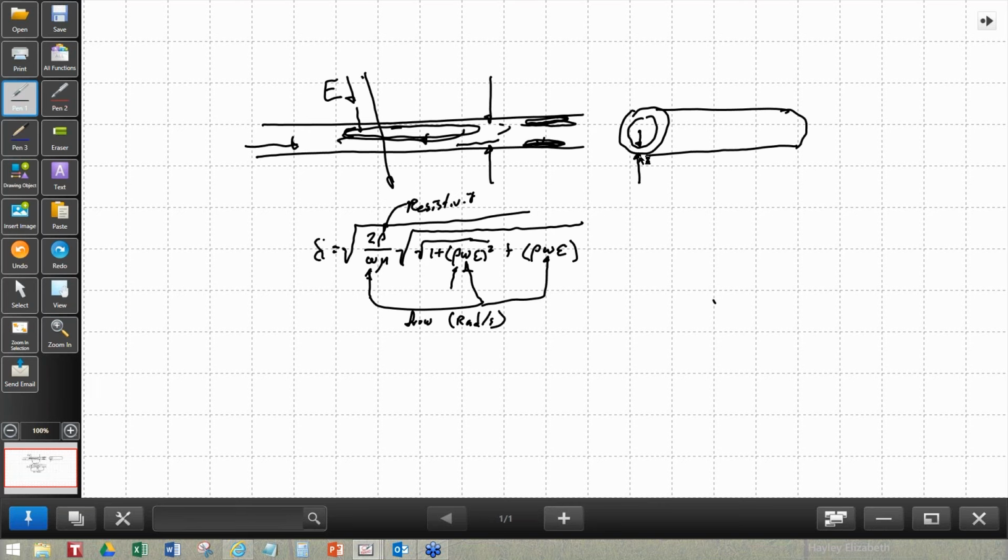Again, the first thing we always want to look at is what is a quarter wavelength. This is kind of a generic rule. If your material is very, very thick with regard to a quarter wavelength, then you're going to start having some effect. If your material is very, very thin with respect to a quarter wavelength, then you're not going to have much effect, because the signal isn't going to be able to push things around because it isn't in one state long enough to do that.